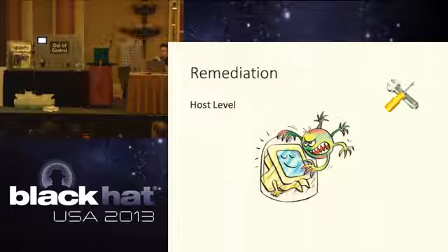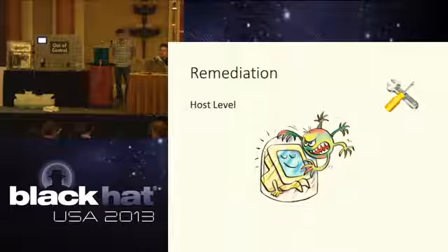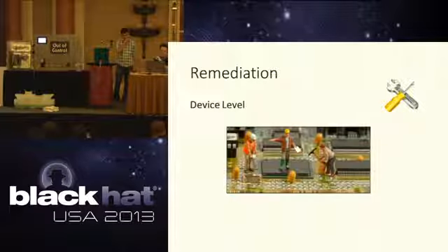Your host-level antivirus is old and antiquated, but it's still the best practice, so it's still used a lot. At the host level, control systems are especially well suited for newer technologies like application whitelisting, because they only really do a few things and they're not used for general purposes. So it will restrict the programs that can be run on those endpoints.